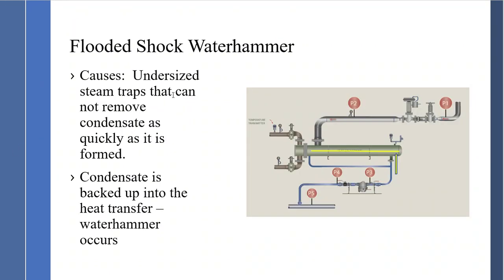Flooded shock water hammer is caused by undersized steam traps. And the thing with undersized steam traps, as I said in the previous segment, or segment 1, in sizing the drain device, you have to take time and effort to understand P3, P4, or the differential pressure across the orifice in the steam trap.